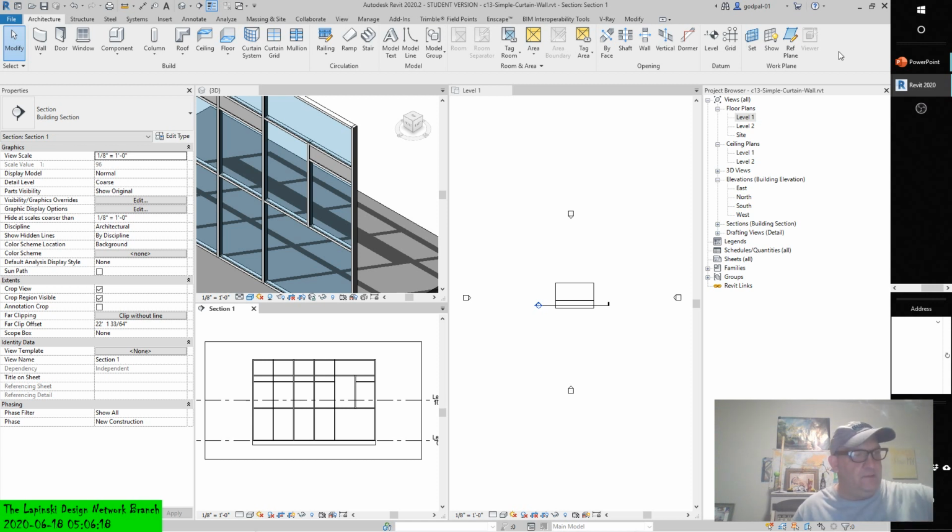Door families for curtain walls can be found in the Doors folder of the Revit default library, but they behave differently than regular doors. The height and width of the curtain wall door are driven by the curtain grids, not the type properties of the door. Follow these steps from the Insert tab in the ribbon.